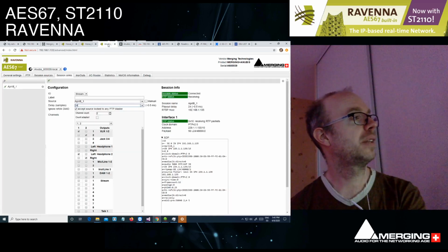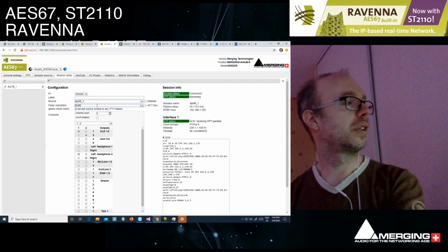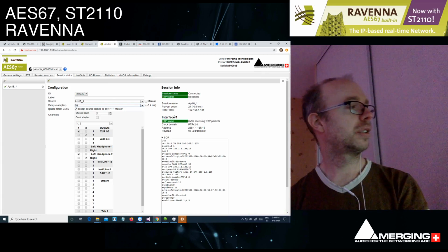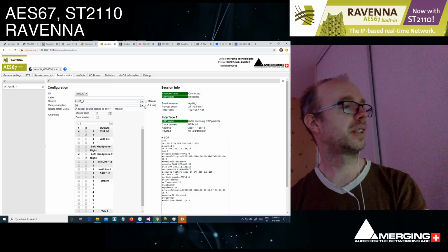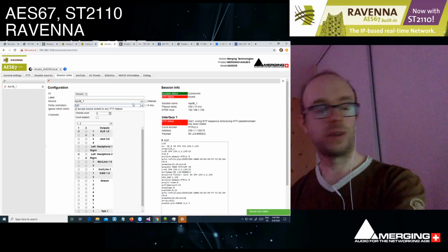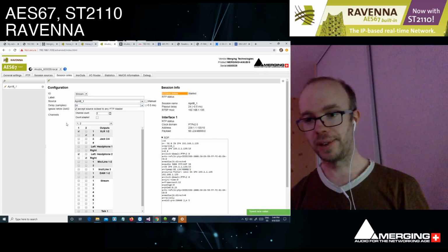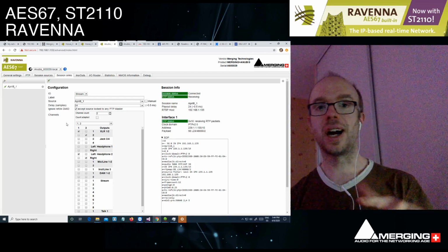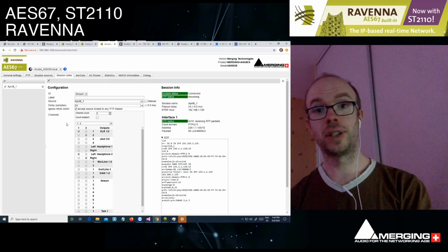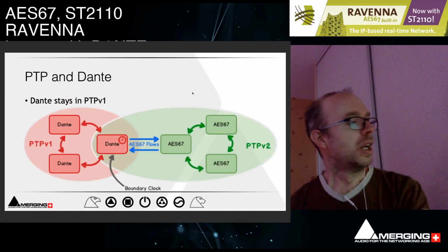And on my Anubis, I cannot receive it if I have a buffer that is lower than twice the packet time. So if I have 20, but you see, it has corrected it. So it will not even accept it to be 24. So in this way, because you have to have a minimum time that is twice or 3 times the sender packet size, the sink latency and the source latency are linked. But it's only a minimum. The maximum is actually not linked to the sender latency at all.